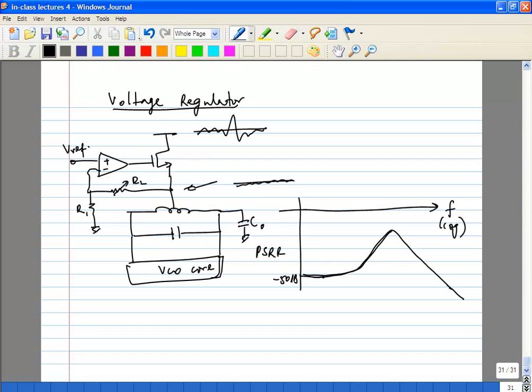This is all common mode noise that is getting detected. Remember, even if you have common mode noise, we talked last week about AM noise, right? Through the varactor, you will always have AM to PM conversion, so that will end up as phase noise. Are we interested only in the PSRR number at omega naught? No, you are interested in PSRR.